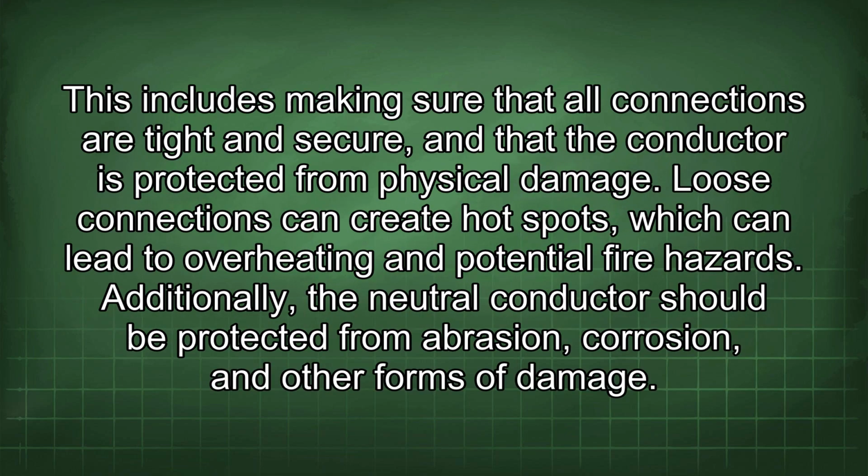This includes making sure that all connections are tight and secure, and that the conductor is protected from physical damage. Loose connections can create hot spots, which can lead to overheating and potential fire hazards. Additionally, the neutral conductor should be protected from abrasion, corrosion, and other forms of damage.